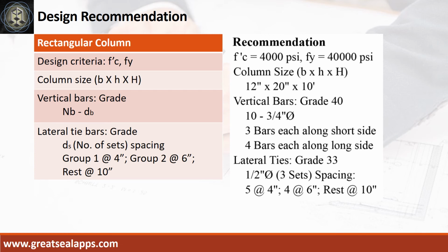Half-inch diameter bar, 3 sets spacing: 5 at 4 inches, 4 at 6 inches, rest at 10 inches.